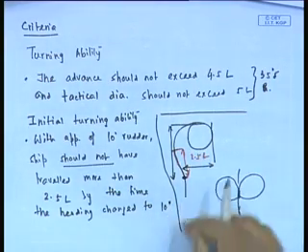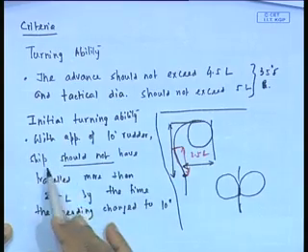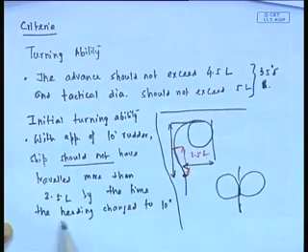What does it mean? Supposing it has gone beyond, it basically means that it is responding very slowly to rudder. After all, it stipulates a condition on how fast it will respond to rudder. Because imagine it is going at full speed, you give a rudder, and it is responding so slowly that it has gone much farther by the time the heading has changed 10 degrees. Not accepted. It says you must have the heading change 10 degrees before you have reached 2.5 L along the x direction.